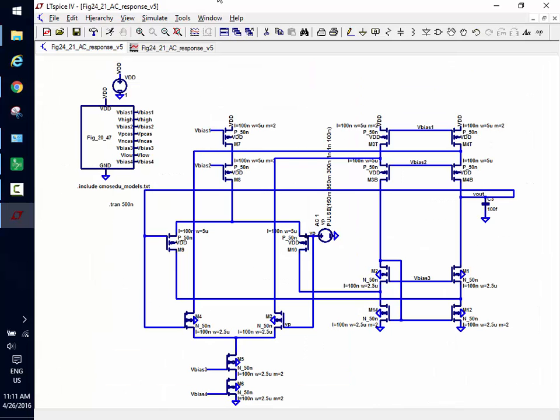When you do your designs, what's going to be different? This is a one-stage operational transconductance amplifier. You're going to have 2 stages, so your output's an inverter. So it's going to be able to swing from VDD minus VSD sat to VDS sat. This one we have limitation of 2 VDS sat, and so the gain starts to drop and it doesn't pull it up.